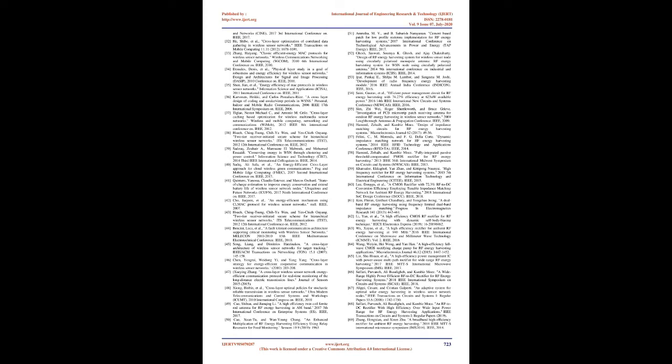Zhang et al. 2017 proposed an exponentially fed charge pumping rectifier design for generating power from surrounding RF energy sources with improved power efficiency. The simulation and measurements reveal that the efficiency is improved by 5% over the ultra-low power rectifier with output DC voltage of 0.7 V amplitude.